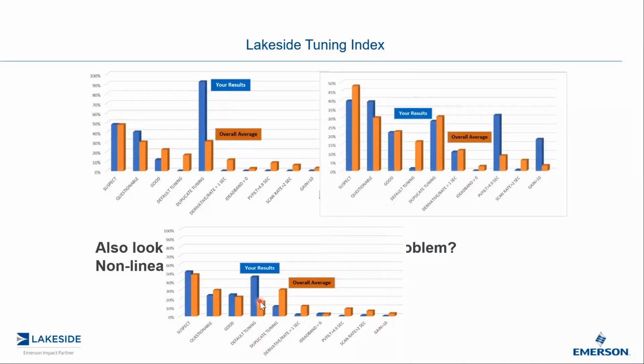And this one here, what stands out for this particular customer is the PV filtering is greater than 4.9 seconds. We suspect that there may be some significant measurement problems throughout their plant. We're also in talks with them, going through each individual loop to make sure that if there is an excessive amount of dampening, why is it? Most of the time, remember we talked about specified, install, and maintain. It may not have been properly specified, installed, or possibly not maintained well.